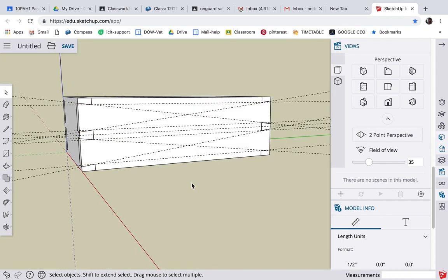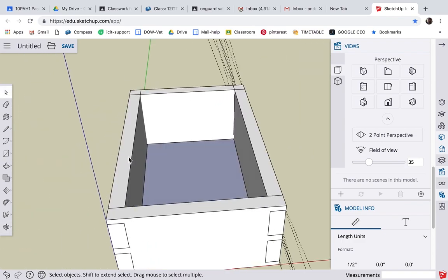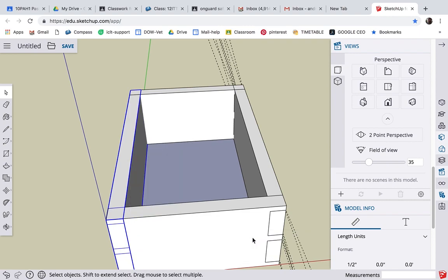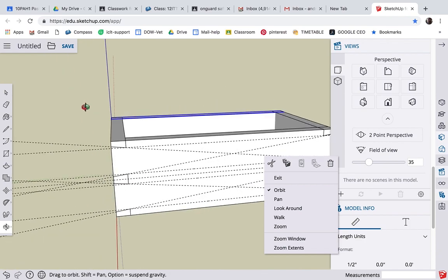So in effect, what I've done is I've drawn the dovetails on the end of this one, the pins on the end of that one. These dovetails have been copied to the back, and these pins have been copied to the other end. Now, in as much as that is a mirror copy of this, it's the same for this back object. So if we select that now, and do the same process, flip along, not green anymore, but red, you won't notice any change, but you will later on when we start putting grooves into that. If you miss that step, your grooves will be in the wrong place.